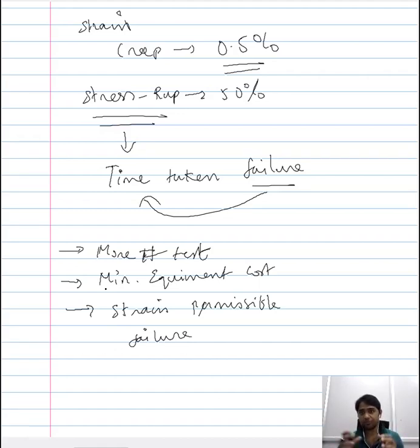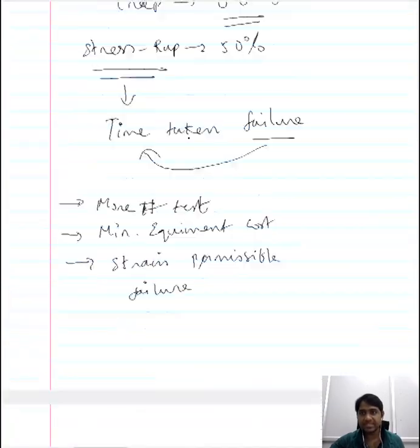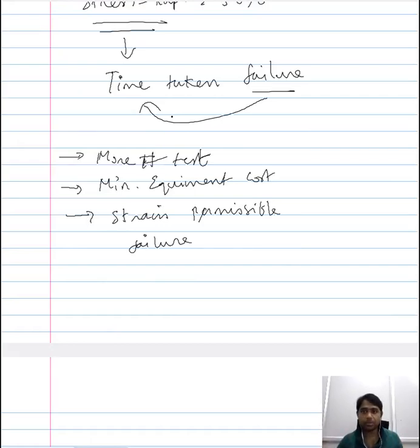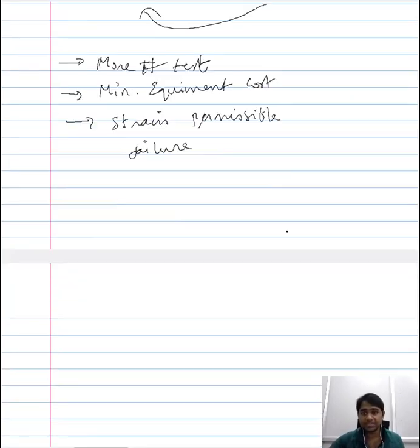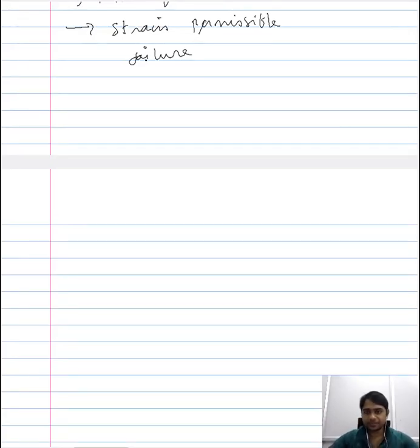So the primary focus of the stress-rupture test is to gain an understanding of the time taken for the failure of the materials, and of course it has some relevant uses in the applications as well. Now, the stress-rupture test allows us to do a significant number of tests for a given duration, considering that each stress-rupture test takes only half of the minimal time the creep testing takes. The results from these several stress-rupture tests are presented in a unique manner, as a combination of the stress and the time taken